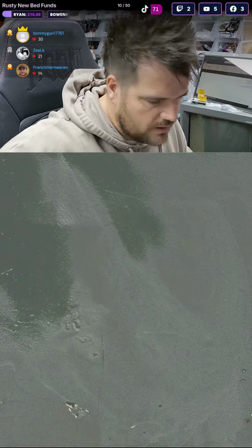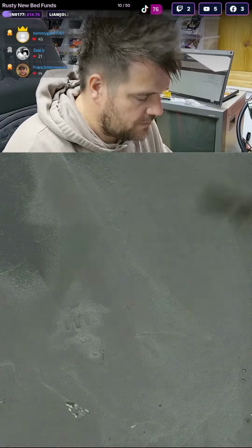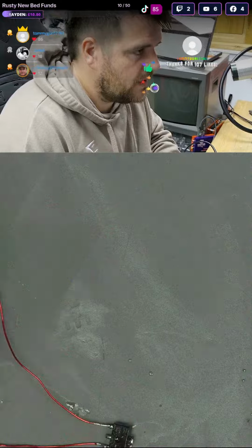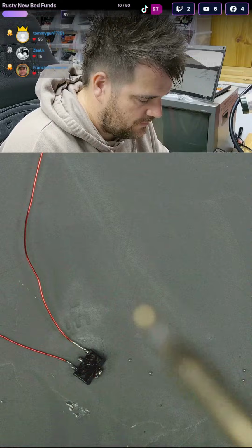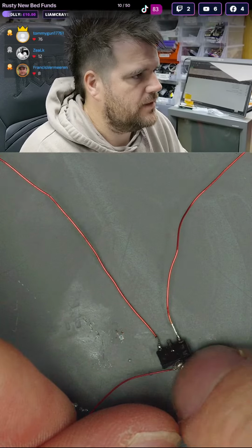Right, so hopefully we have got to do this quite a few times. I was going to say hopefully we haven't got to do this amount of work on every component, but looks like all the transistors are like this. But the benefit here is I'm going to have these wires pre-stripped, pre-tinned and saved in between testing, so all I'll have to do is tack the 3 wires on, and I'll leave them attached to the tester as well, so it won't be anywhere near as long as this then. We'll just have to tack 3 solder pads on each one. And the middle pin is attached to the tab at the back as well, so that is effectively the same as that middle pin.